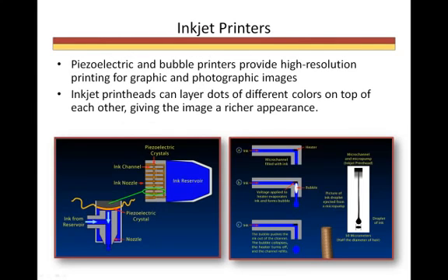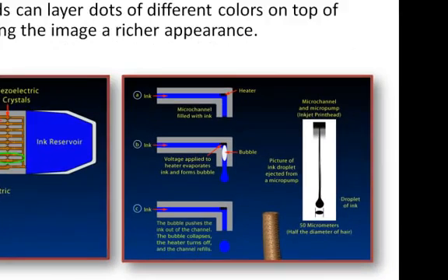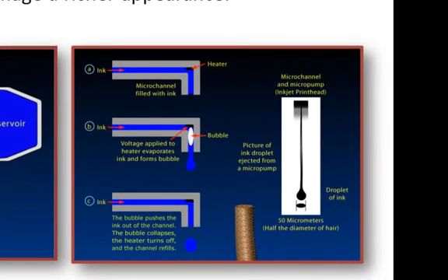Another commercial application of MEMS, which you are probably very familiar with, are the inkjet and bubblejet printers. In the bubblejet print head, heat is applied locally to a microchannel filled with ink. Very quickly, or in 100 microseconds, the ink evaporates, forming a bubble. The bubble forces a tiny droplet of ink out of the microchannel and onto the paper below.